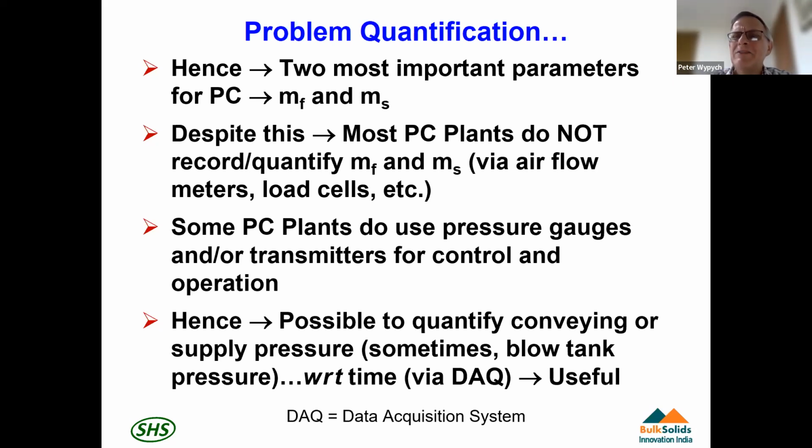But don't ever trust a pressure gauge. The first thing you do is tap it and make sure it works. And the second thing I would always do, put quick connect couplings in there so that you can always take it out, put a new pressure gauge in there and make sure that you're getting the same reading.